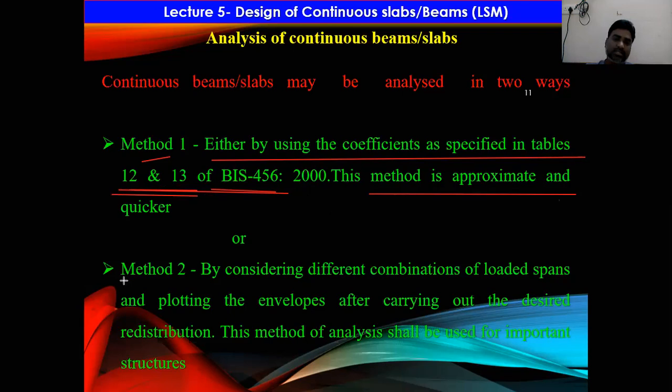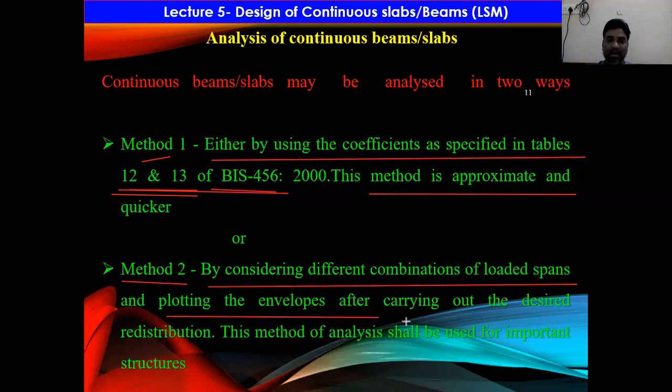The other method, method 2, is by considering different combinations of loaded spans and plotting the envelopes after carrying out the desired redistribution. This method of analysis will be used for important structures, right? I think you studied in your previous year, in theory of structures, I think in the last unit, there is a method called the moment distribution method, right? I hope you all remember the moment distribution method.